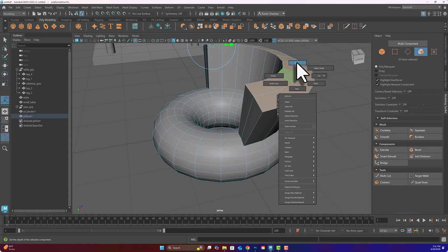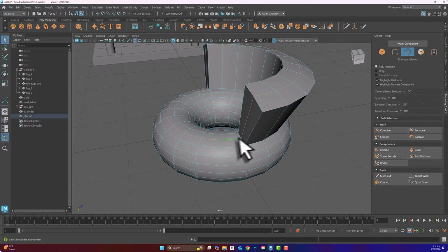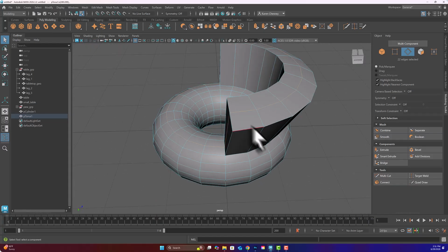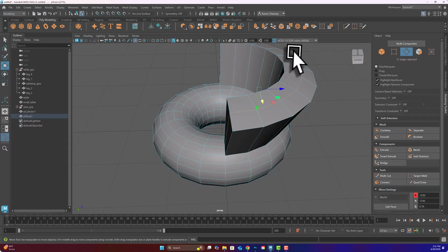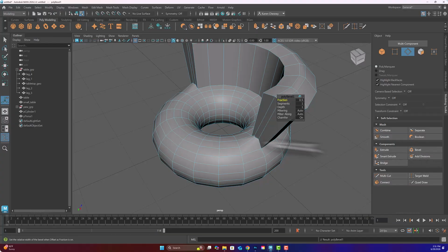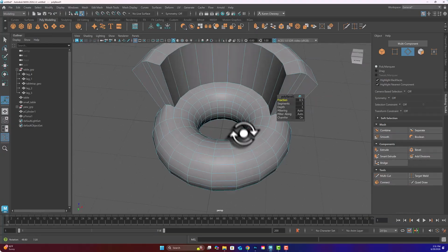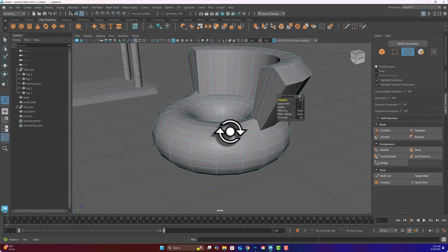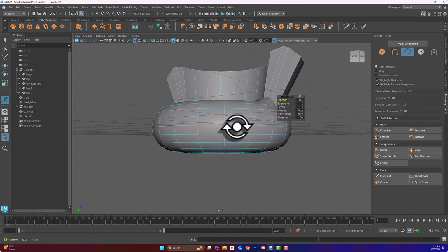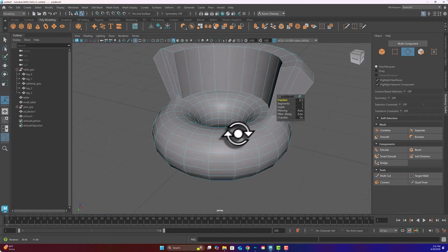And maybe I'll grab this edge loop. I don't want this part of it, so I'm going to say, not you. So I just have this edge loop. Maybe I'm going to raise that up a little bit. Maybe I'll bevel that edge. So this entire floaty thing is made out of probably one piece of plastic or a couple pieces of plastic or an extruded piece of whatever.